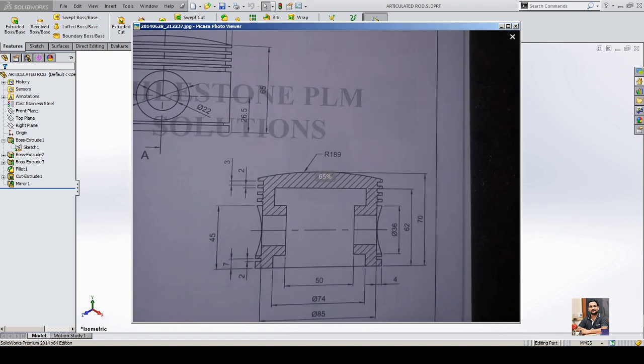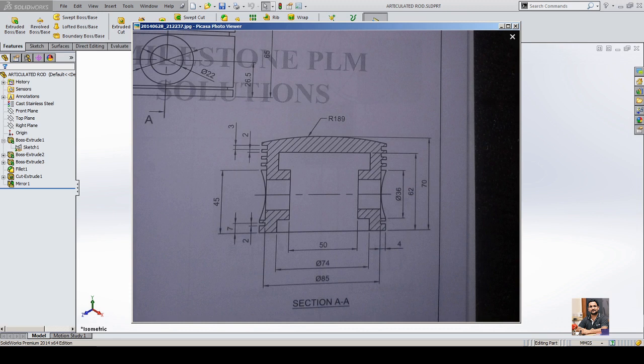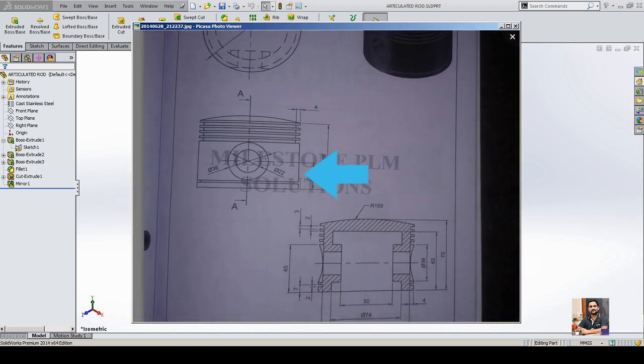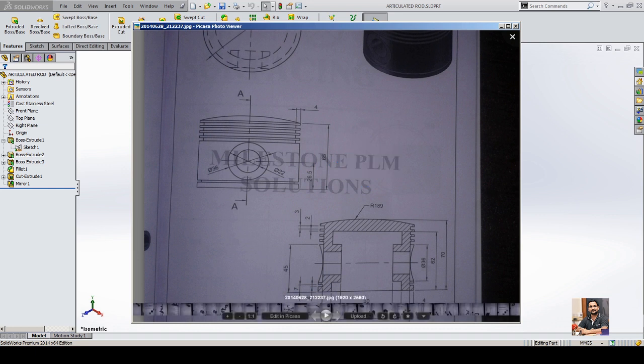And we have a cut cross section here, and the cross section says that, if we consider the axis over here, the shape is this. This is what we are going to sketch and revolve. But before going ahead, if we just have a look at this part over here, there is nothing like this over here, right? This face is straight. Okay.